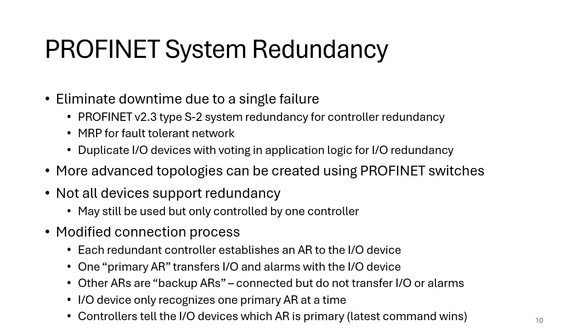So you have two controllers operating typically in hot standby mode. Those controllers would be synchronized using some separate synchronization mechanism. We're not synchronizing over the PROFINET network, we would synchronize using an external network. So depending on what PLC you're using, they would have their own dedicated Ethernet cable, or it might be a fiber cable, or they might even be unsynchronized and you just assume that the outputs are synchronized because the inputs are the same, because they're coming from the same input module. So this allows you to have the hot standby controllers.